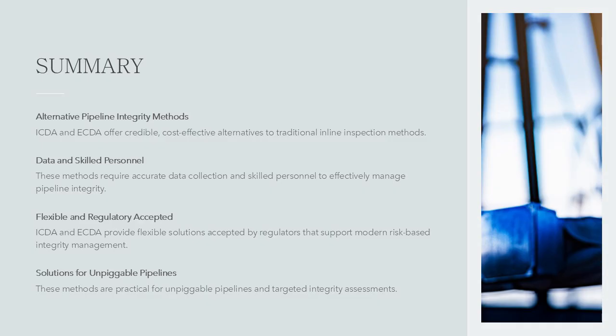ICDA and ECDA are credible, cost-effective alternatives to ILI for pipeline integrity management. They require accurate data and skilled personnel but offer flexibility, efficiency, and regulatory acceptance. For unpiggable pipelines and targeted integrity checks, these methods provide a practical solution that aligns with modern risk-based approaches and industry standards.